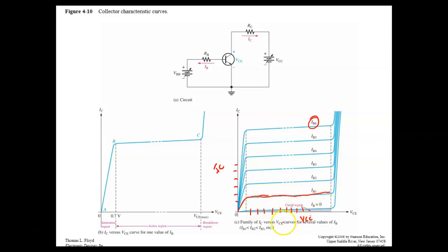And then I can get a feel of what the transistor is going to do. Later on, we'll see that we can put a slope between saturation and cutoff. Then we can come up here and actually see what this thing will do when we put it in an active circuit. This is a transistor load line, right?